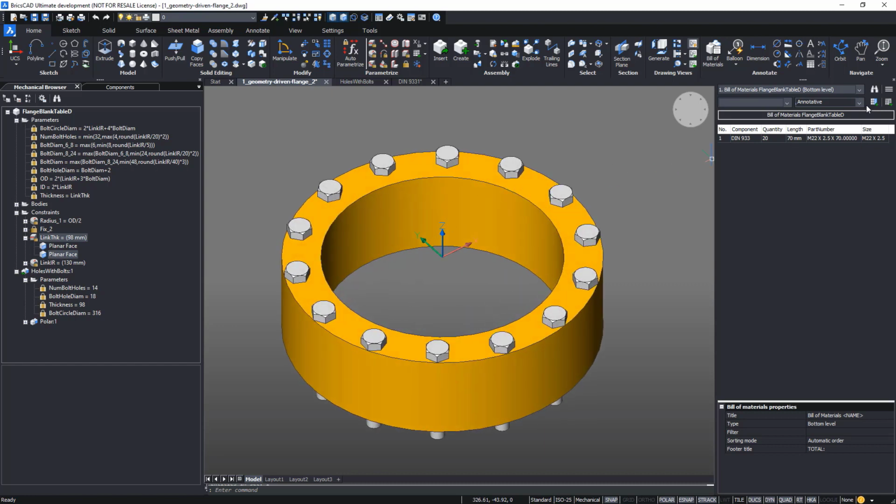And what is interesting, these values can be used as the parameters of other parametric components, the bolts in this case. And still, the design table is still in action. So if the changes in the geometry match one of the configurations, you can see using our bill of material panel, which is also a new one and will be explained a bit later, that the sizes of the bolts, even after direct modifications, are still chosen from the design table.